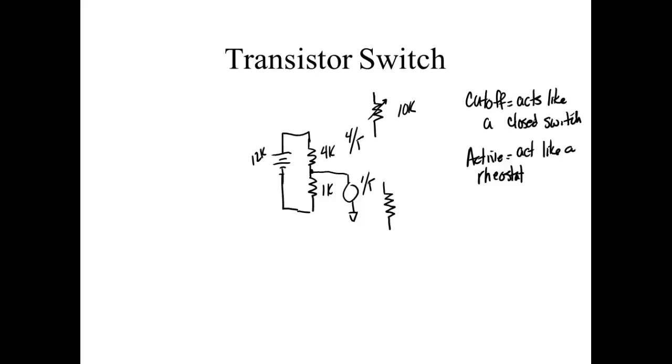Well, the voltage divider is just that, and that's what a pot is. A pot is a variable voltage divider. So that means if I have a 10K pot, and this is 1 and this is 3, the resistance between 1 and 3 never changes. So if it's a 10K pot, if I measure between 1 and 3 out of circuit, it will always measure 10K. So what you're doing with the pot is you're doing this.